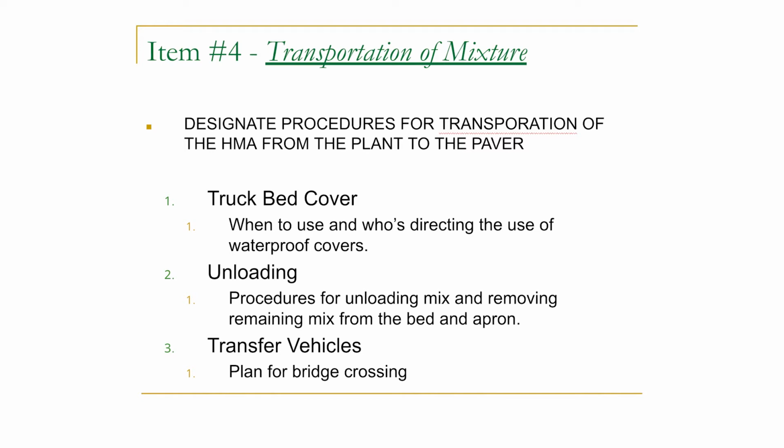Unloading, your procedures for unloading the mix and removing the excess material from the apron. So spell out, is the truck going to stop shy of the paver to avoid the bump? Like Brad said, basically spell out what you're going to do. So INDOT, everybody knows, everybody's on the same page ahead of time, so you don't have issues once you get there. Your transfer vehicles, in ours, I think we say we reduce it to 50% capacity before we cross the bridge. So those are just items that you should include in there.